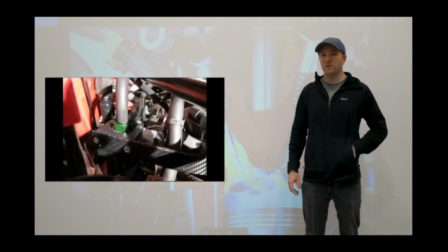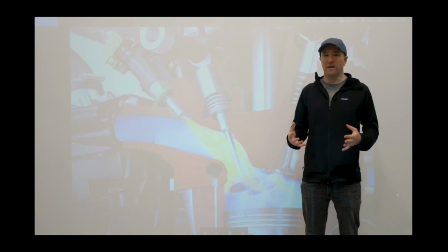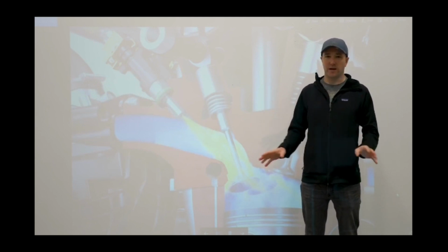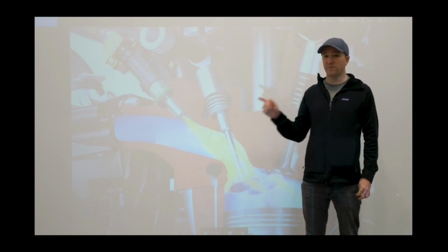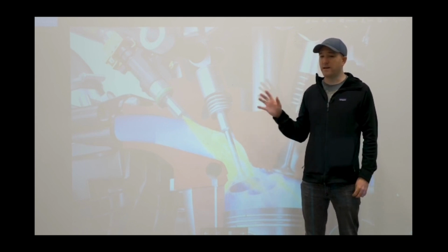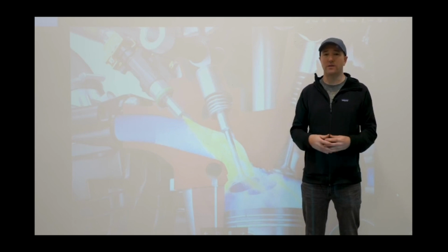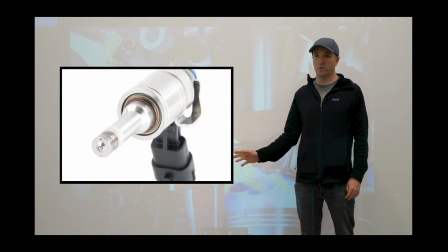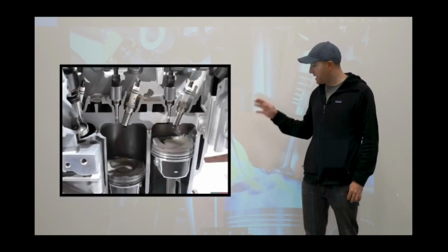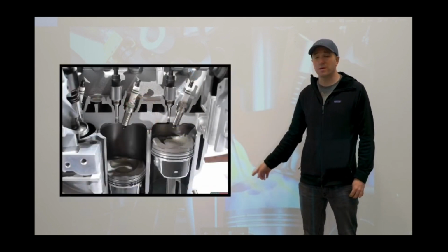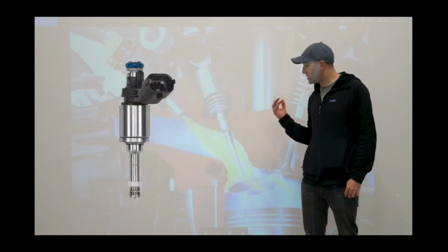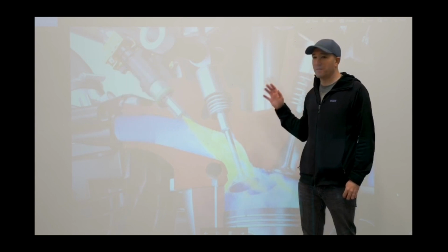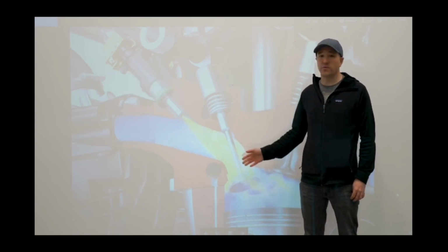The next thing that you can do to help with this is, people talk about using fuel additives. Fuel additives will do nothing for a direct injected car except keep the direct injectors clean. And this is the next thing. You should use fuel additives if you have direct injection, because these injectors are a lot more sensitive than port injectors, not only because they're exposed to extreme high temperatures, but because they're exposed to a lot more carbon buildup that can get into the nozzles, that can block them, can affect fuel flow.